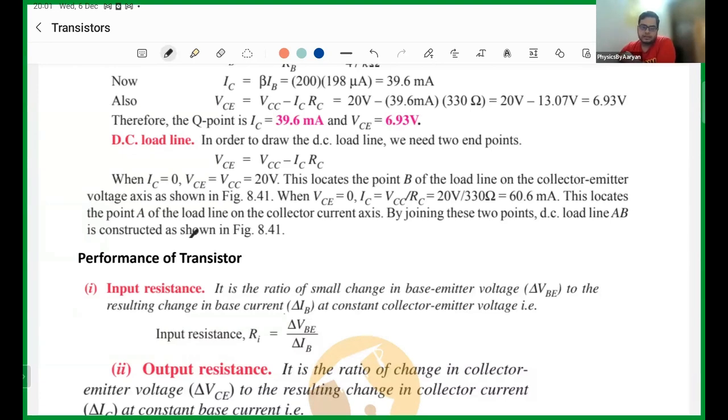So that is my base. If oscillations are happening, what is the best point around which I want my oscillation? If my transistor is fluctuating itself, or you can say the point where the load line is, that is also one of the mathematical definitions, not the lab definition. The point where this line and this line intersect is also known as Q point, right? The point where your output characteristics and load line intersect is also known as Q point. What is your explanation?